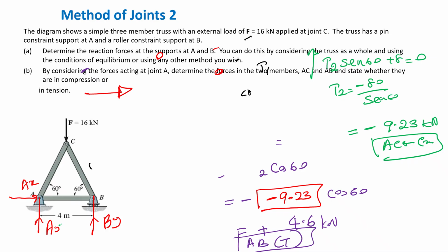What are the forces in the x direction? For this one, we don't care about the members. You consider the whole truss. Your free body diagram is the truss. Do you have any force except at AX? Consider T1. No, because when they are together, they are actions and reactions. When you take them off, they are two separate loads. They are internal forces. Till you keep them together, internal forces won't affect. So they are actions and reactions.